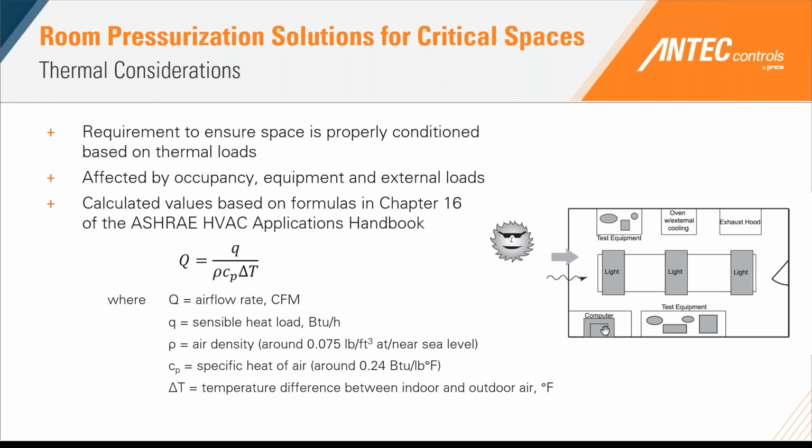So thermal considerations are going to be a very big driving factor for us in these spaces. We want to ensure that our critical space is properly conditioned based off of the thermal loads. In a lab application, you may have a large number of additional equipment generating thermal loads that may need to be covered. On the other end, with healthcare, that might have a variety of different types of equipment that needs to be considered. So with that, again, ASHRAE outlines in chapter 16 a very simple equation that I'm sure a lot of you are familiar with on how to determine and calculate airflow rates based off of these thermal loads.